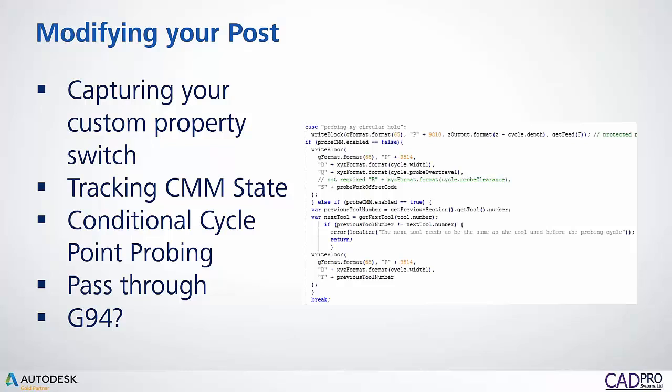But we were able to pretty consistently show that we had a Haas VM3 at L3 Communications that measured within 2 or 3 ten thousandths of an inch. That was more than enough for what we were trying to do, and because of our documentation, we were able to include that as part of our inspection process on some features.